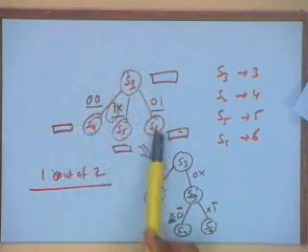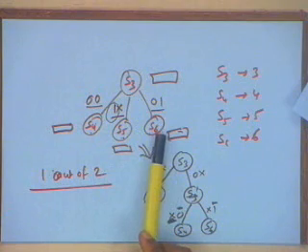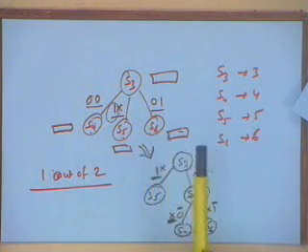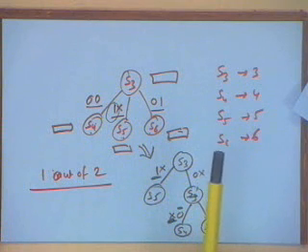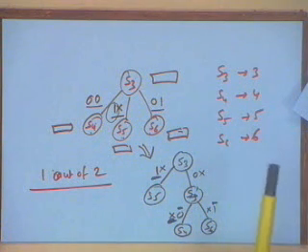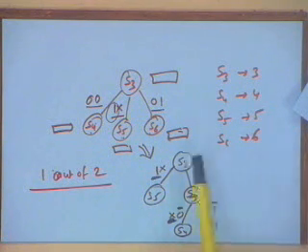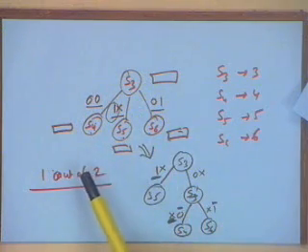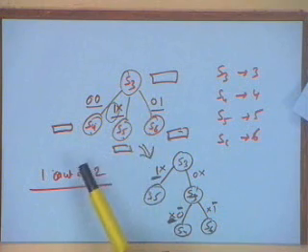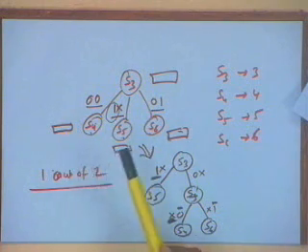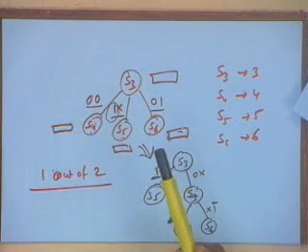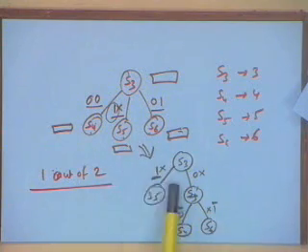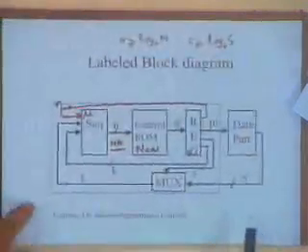So doing this type of implementation in a state machine is not a problem at all. But doing this type of implementation in Microprogrammed control can be very expensive, and we will see the reason for this. Primarily you have to store more than one address in each micro instruction, and that will mean that the size of the micro instruction will keep on growing. And if it is not very often that I need a 3-way branch, and mostly I will only need 2-way branches or no branches, then all those bits reserved for the next address will go to waste, and that is the reason that one typically tries to do it in this manner.